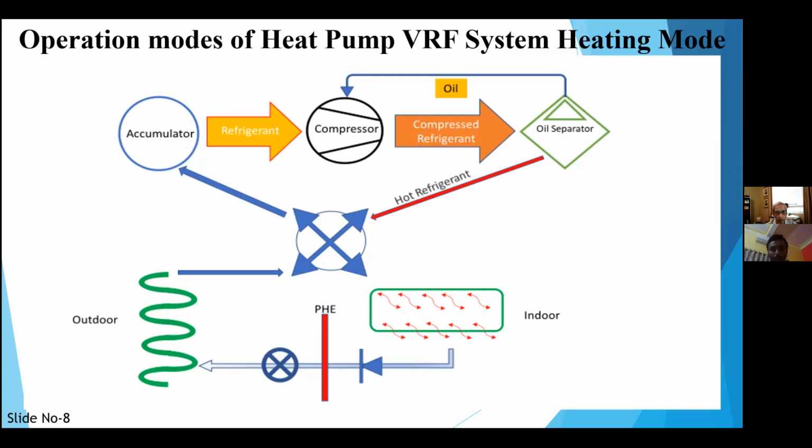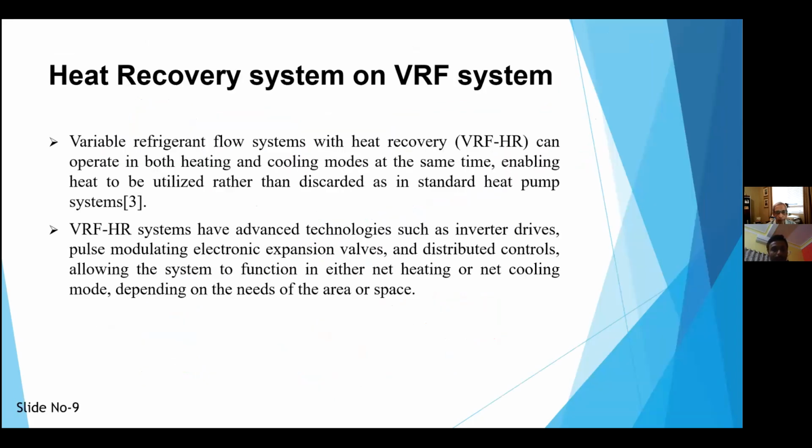This cycle is completely working. So the next is the heat recovery system of the VRF system. Actually, we know that the VRF system has a heat recovery that can be operated in both heating and cooling modes at the same time, enabling heat to be utilized rather than discarded as in standard heat pump systems.